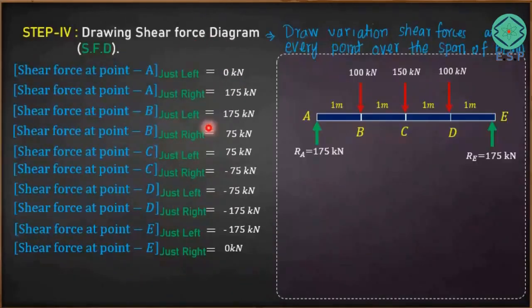You can see here, this is the free body diagram of the beam. We have already drawn that earlier. So what we do is we represent the beam and we represent all the forces acting on the beam. Now we want to get shear forces acting on the beam along its length at each and every point. So I have just marked all the points by vertical lines. This horizontal line will have shear forces on it.